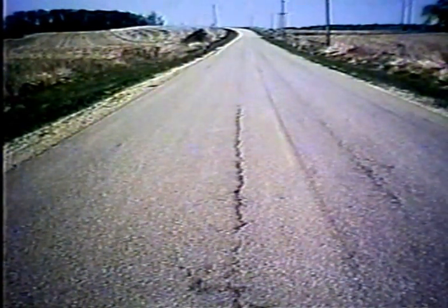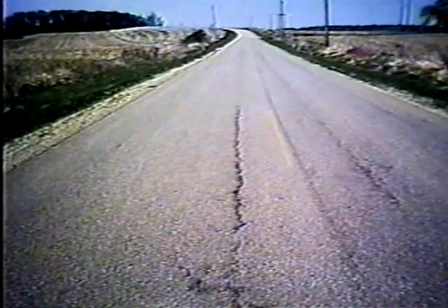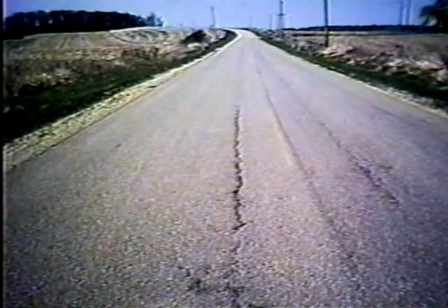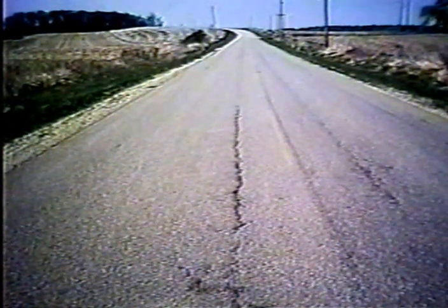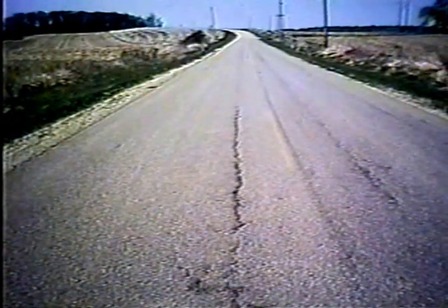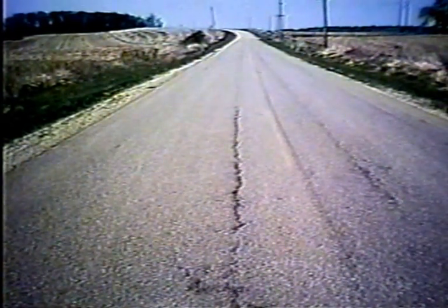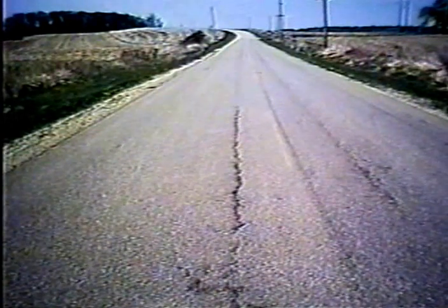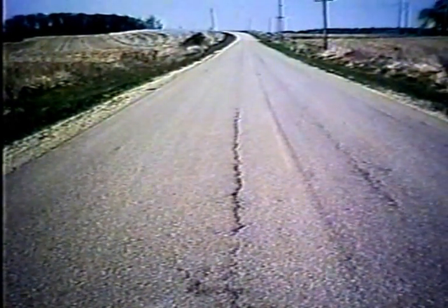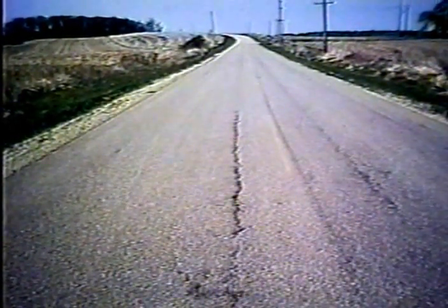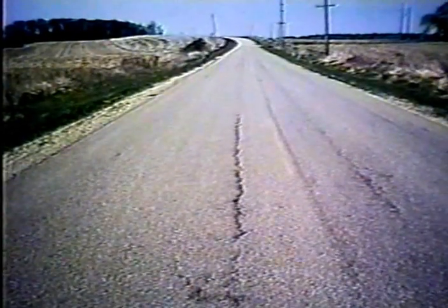Here's another longitudinal crack, but frankly this is quite different. If you look closely, you can see it occurs in the traffic lane, and this is load related. That is, heavy loads have caused the pavement to crack and eventually work its way to the surface. These load related cracks start at the bottom of the pavement and work their way to the top.